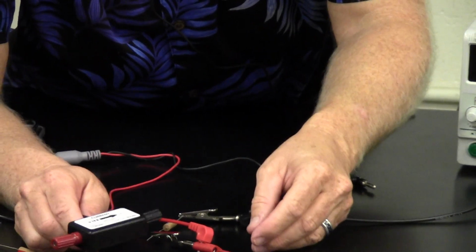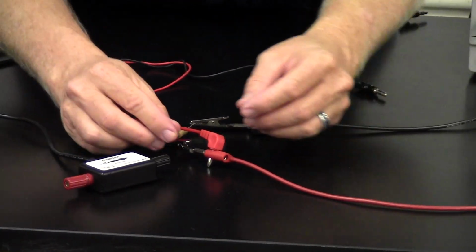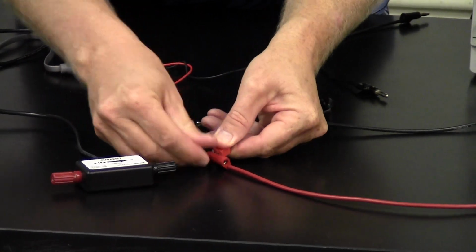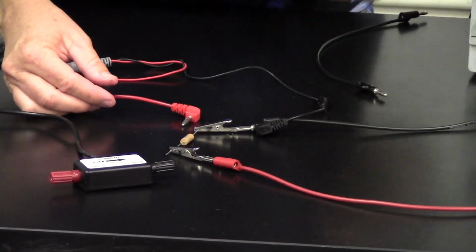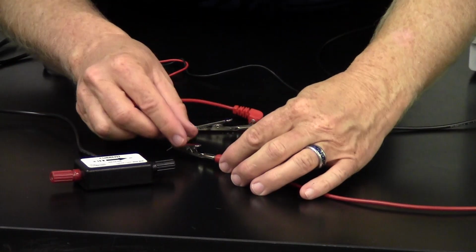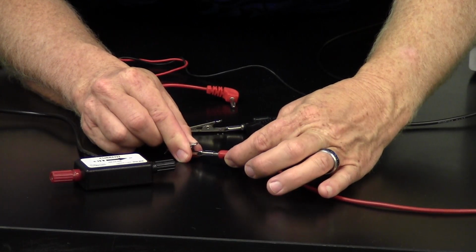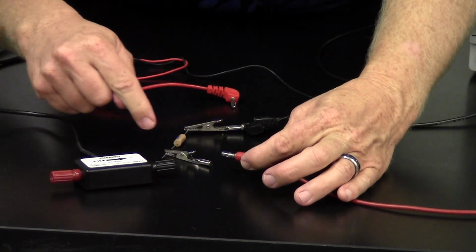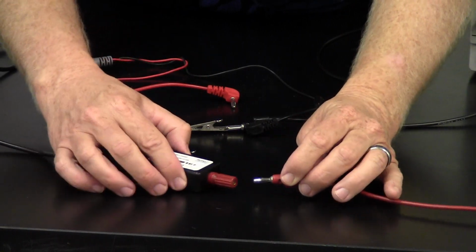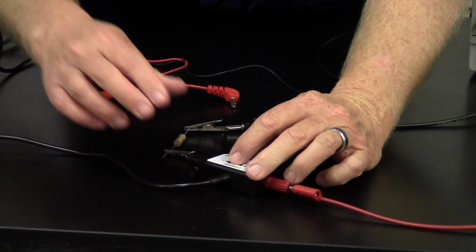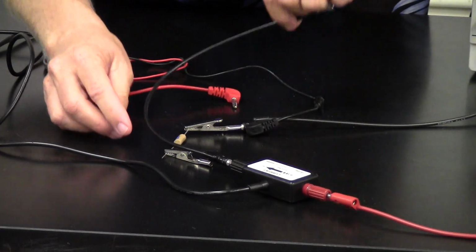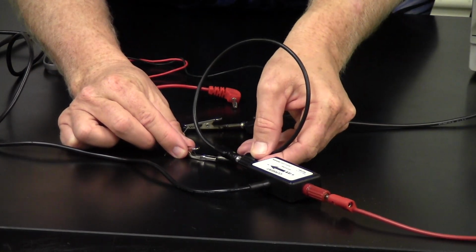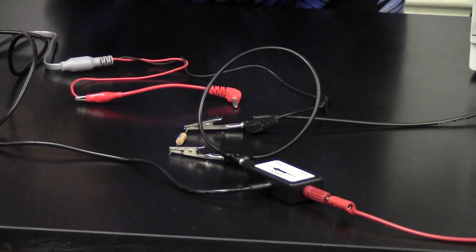All right, so coming over to here, and let me just... I'm going to have to temporarily disconnect the voltmeter to do this well. So I'll just temporarily disconnect that one. But see, the current was coming out of here, so I'm going to open the circuit right here, because that's where the electrons will be flowing. I'll feed it into the ammeter, and this is why I need another wire, so that when it comes out of the ammeter, it can continue on to that resistor.